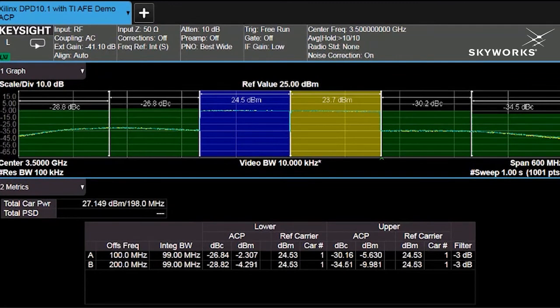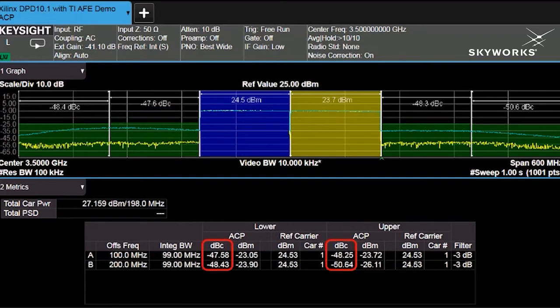But let's take a look at the signal analyzer. So there are 2 5G carriers there, 100 NR carriers. Now we will activate the DPD, and the yellow trace will show the corrected performance. And again, as highlighted, excellent adjacent channel power performance.